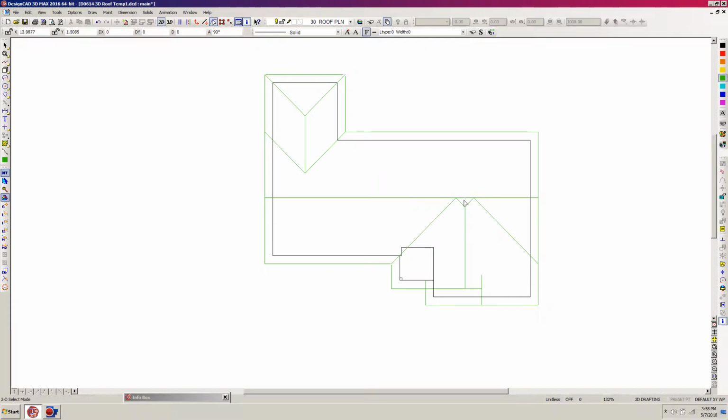And I have to get rid of this little ridge line through here because it does not continue through. So I'm going to go over here to my trim lines and just hold the left button down and go over here, and down in the lower left hand corner you can see it's telling you what it is. I'm going to trim the part of a line that lies between two other lines, and here it gives you the instructions. The first point is the line to be trimmed, and points 2 and 3 are the intersecting lines you want to trim it between. So I'm just over here anywhere, clicking on the line that I want to trim, and clicking on the 2 lines that I want to trim between. Bingo, there it is.